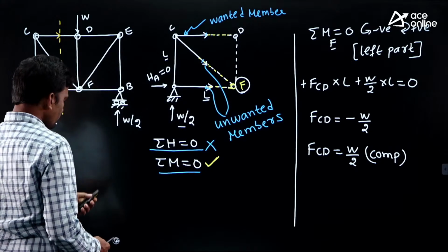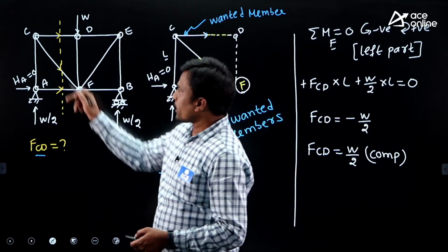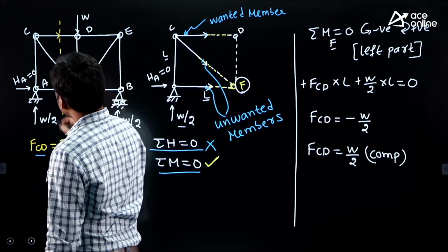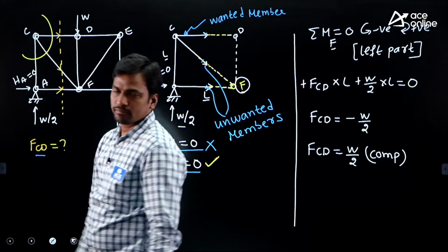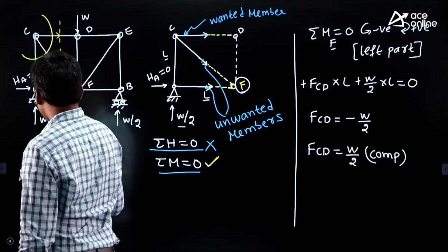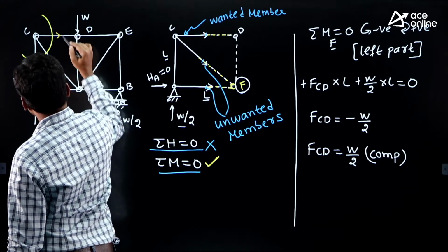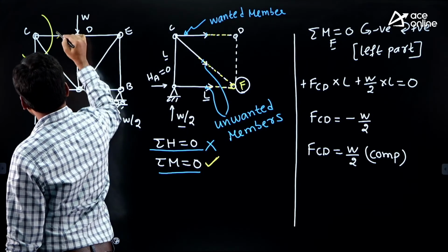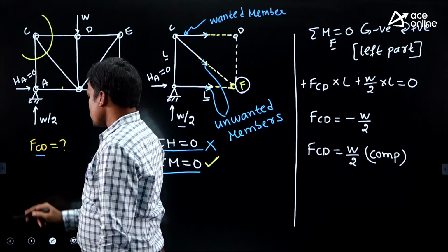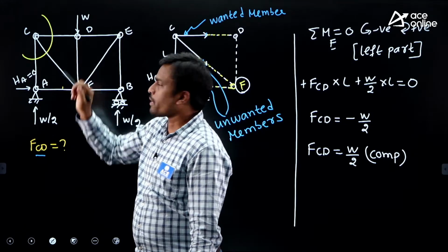Right. Okay, and a few students may get a doubt. Sir, why are you cutting in the vertical direction, sir? I'll cut the structure like this. Just I'll remove this vertical cut. Right. Now check it. First condition, is the section passing through the selected member or not? Yes, the selected member is CD, na? Yes, the section is passing through member CD.